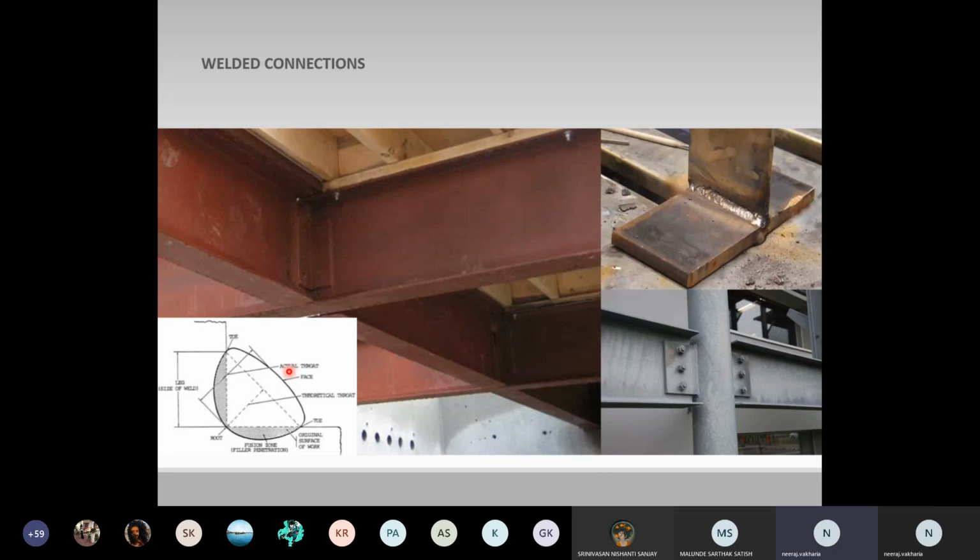So the disadvantage of this connection is that it is very stiff and very rigid compared to the rivets and bolts, because there is some space for flexibility in those connections. Not literally, but there is some ductility in those materials. Here we are making it a unified metal piece, which might lead to deformation in joints at a later stage.